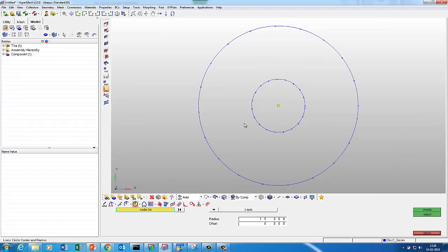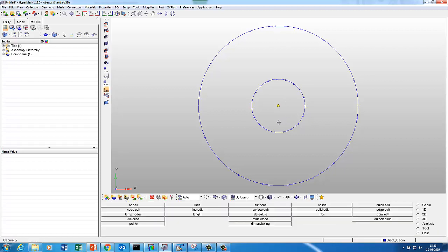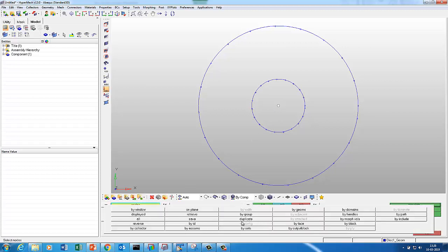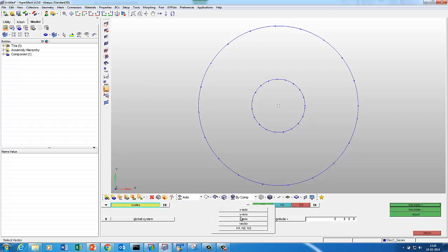So I created the disk, a 2D disk. Then I'll copy this by 25. I'll do Shift F4, and I say node, and I say node duplicate along Y, and I'm just copying it by 25 millimeter.